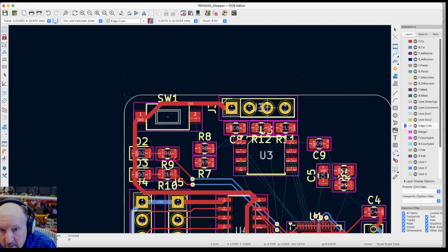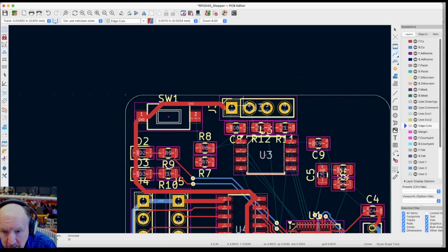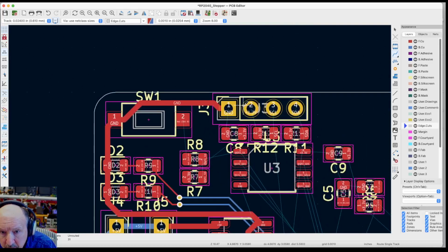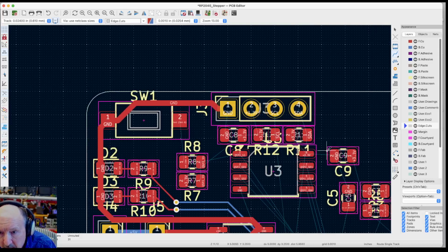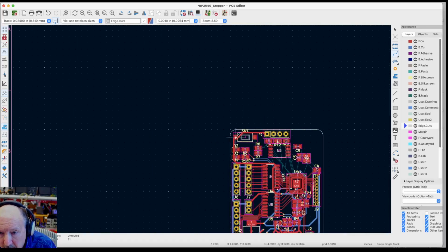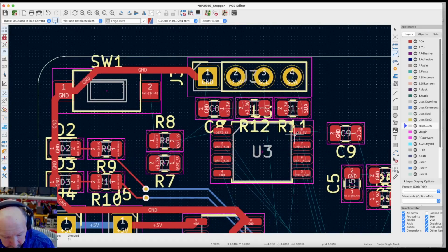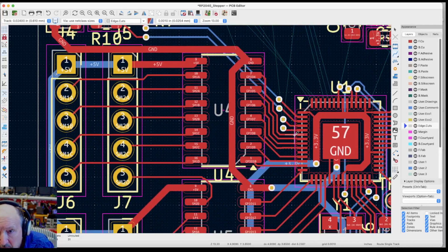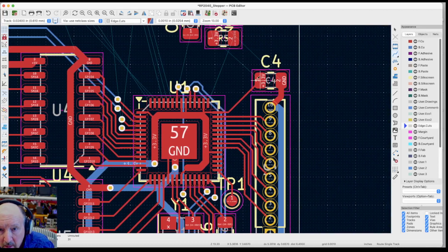Now those are signals. And I still got the 3.3 line that needs to come in. It needs to go there, it needs to go there. What do I got over here for 3.3? That's the 3.3 bus there. There's the first one that comes up. I might go ahead and throw a via on the 3.3 line.